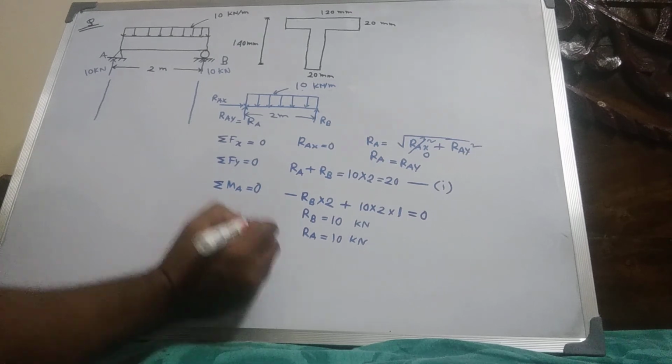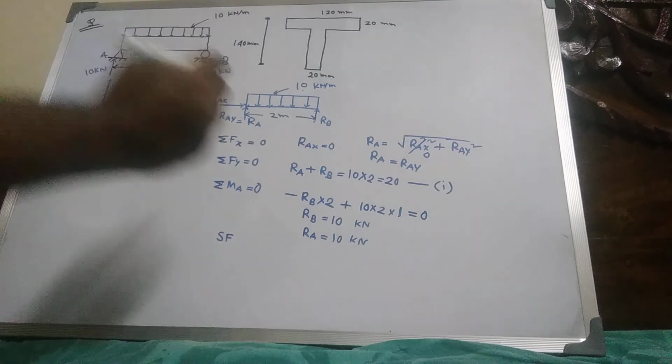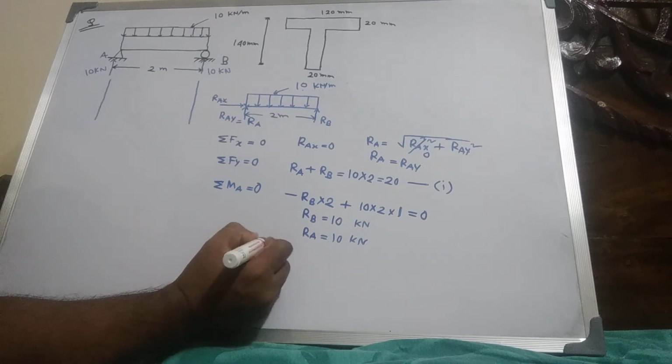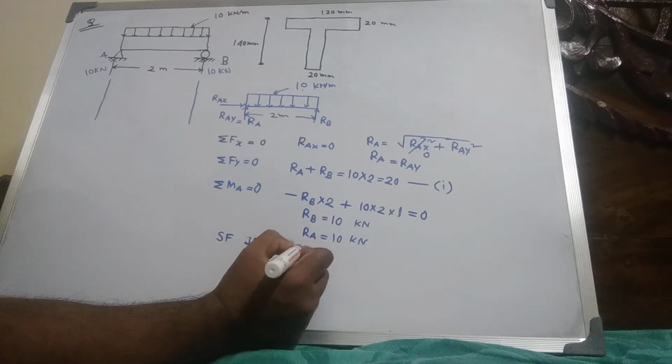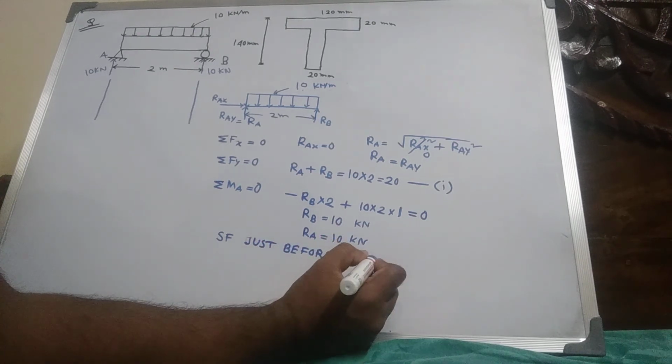Now draw the shear force diagram. At a point load we calculate the shear force twice. Shear force just before A is 0.